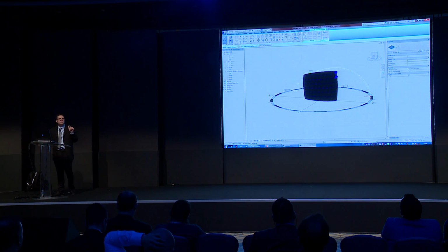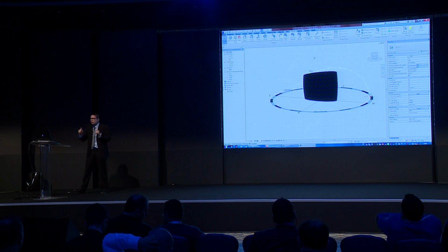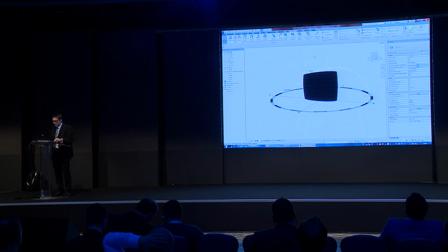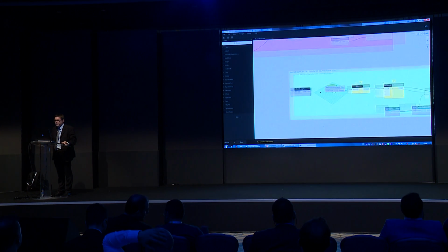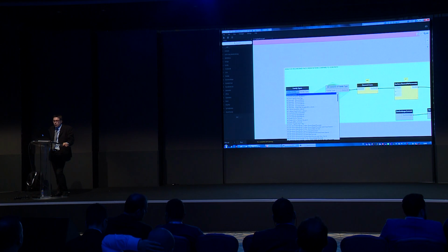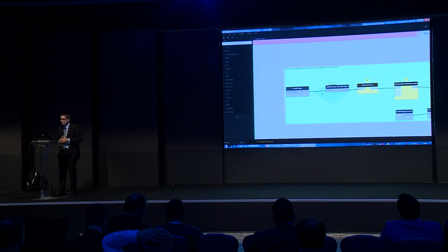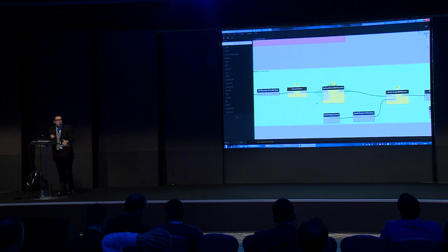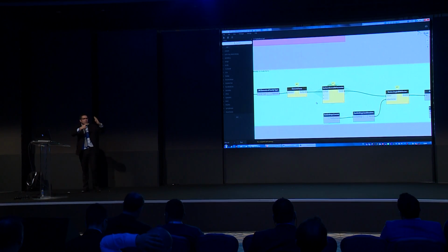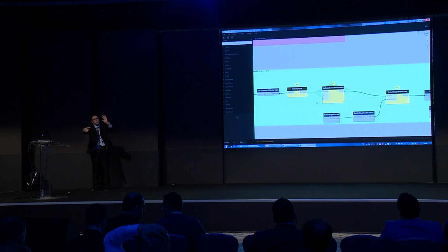Now you've got a physical object in Revit using my adaptive panel. Now the next step is to make a sort of simulation, like a radiation simulation. Not so hard to do this. Okay, it is this part. First, I will use my family that I use to create the exterior shape of the object, and I will extract the normal to this face. Okay, one face, we've got a normal vector, another face, another normal vector.